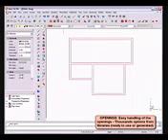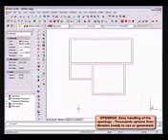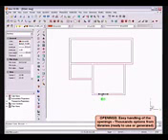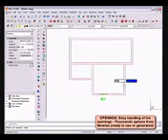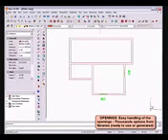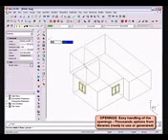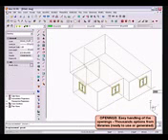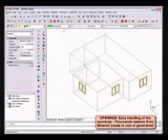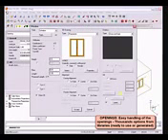Here we'll insert some windows from the library provided. These doors and windows are also intelligent objects. They are inserted in the wall you specify, and the software adjusts the wall accordingly. All these objects are parametric. You can edit the window with a simple double-click on it to display the dialog box, or simply drag the grips of the object.